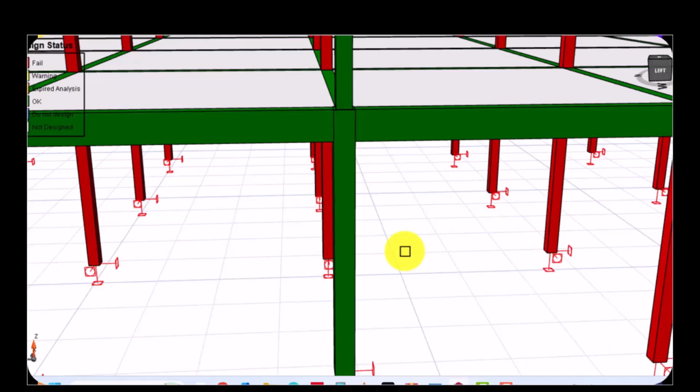If we stick to good construction practice, there will be a reduction in column failures. Apart from that, we also have scenarios that I explained earlier, of being on site and adding additional stories on top of a building that is only supposed to carry 2 to 3 stories.